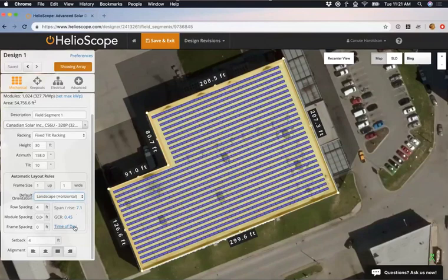day tool. Now, before I show you, I will just put in a word of caution. If you're using ballasted racking, I'd recommend talking to your manufacturer about what that row spacing can be for the ballasted racking product, because a lot of times they'll have it restricted to say, well, you can have these tilts and you can have this row spacing. So always reasonable to consult your manufacturer before you actually go in and start playing around with ballasted row spacing. But that said, if I do have the ability to play around with this, I can click this blue time